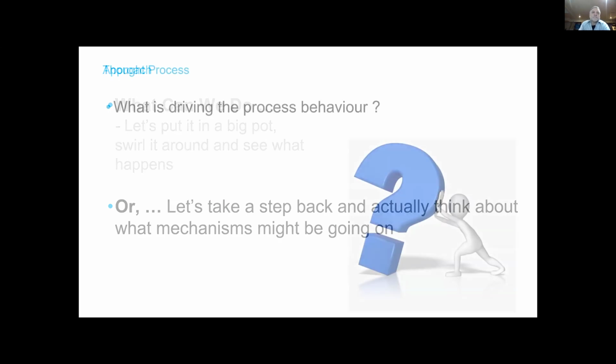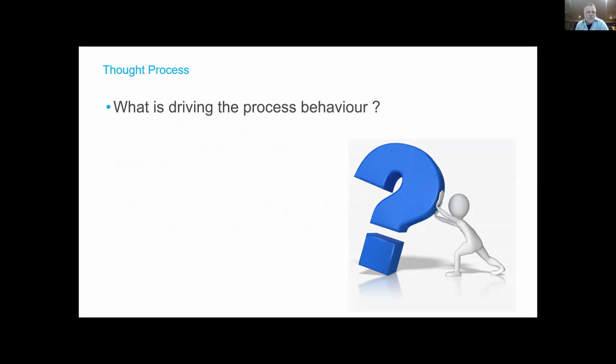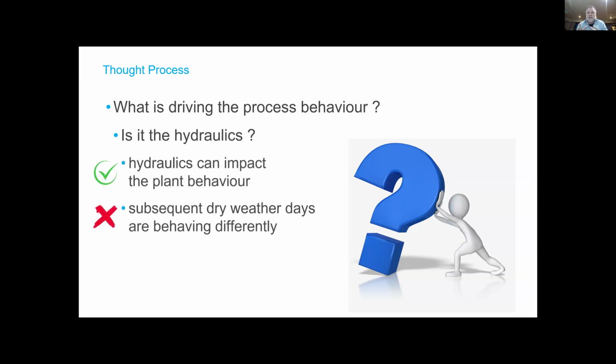and to adjust your model accordingly so that it captures that behavior. So we have to think back about, okay, what is driving any kind of process behavior? Why does nitrification change at any given moment in the day? And sure, is it hydraulics? Sure, absolutely. Hydraulics will have an impact on how the plant behaves. Movement of solids, nitrification behavior, retention times, all of that stuff. And if we looked in this particular case, we know that the hydraulics can potentially have an impact, but we have subsequent dry weather days, sunny days, where I'm actually at the plant watching this treatment plant, and it behaves completely differently on two seemingly identical days from a hydraulic point of view.